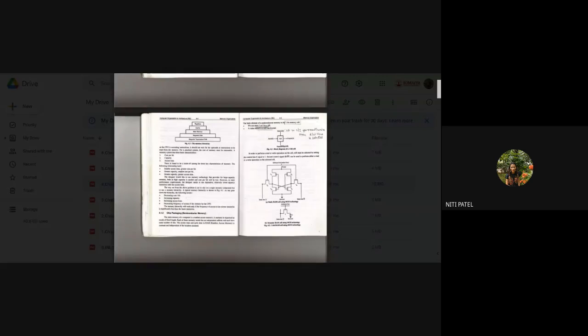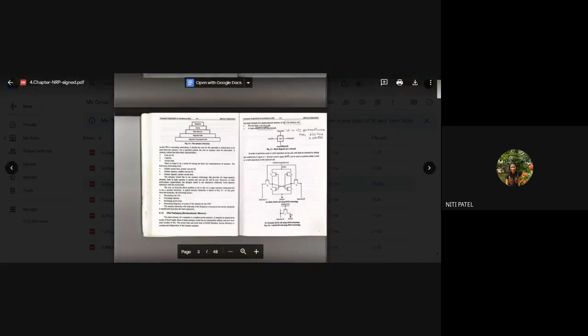Each memory cell will keep changing depending on what it is used for, either SRAM or DRAM. Some more components will keep getting added, but the working of this cell part always remains common. Maybe in SRAM a few more hardware parts are added, and in DRAM they might remove something. The hardware keeps changing from memory to memory, but every memory works on the basis of this cell, where we store the value 0 or 1. How the cell works depends on the input activation of select, which further activates your read and write signals. Is that clear?